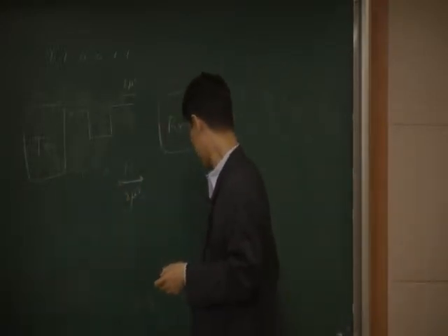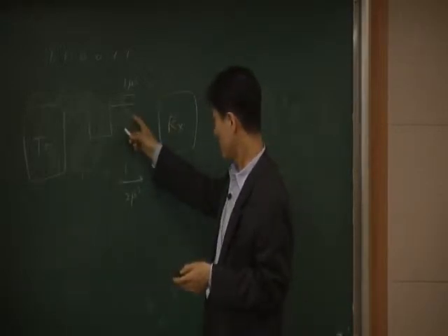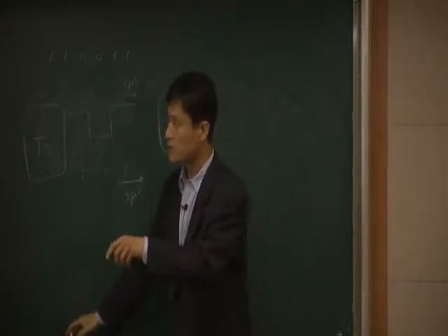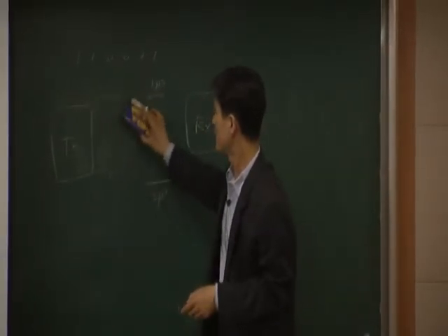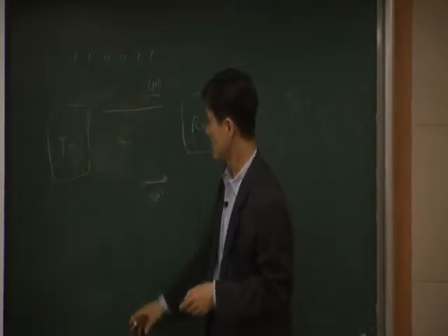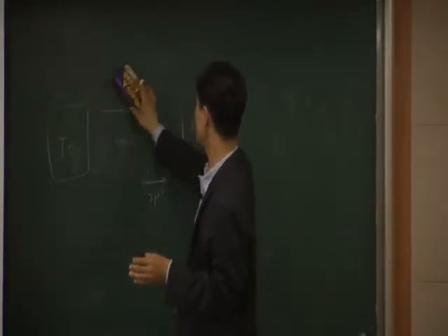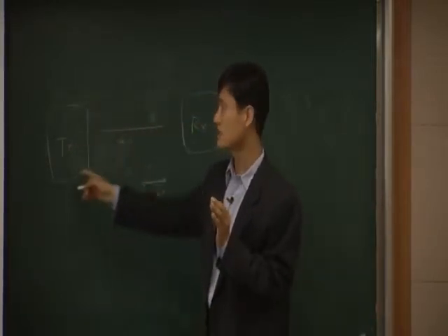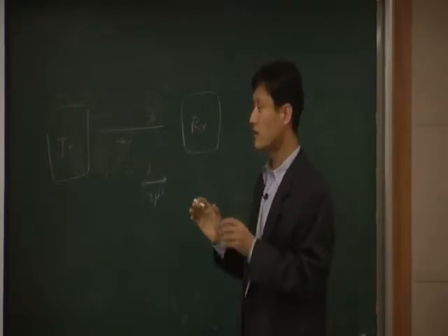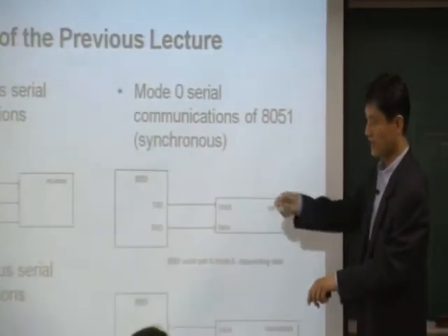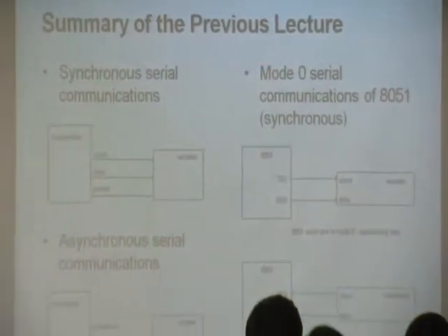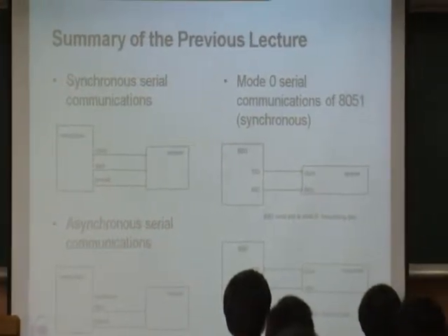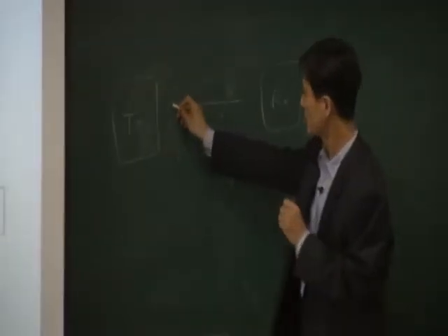And not only that, we have only 0 and 1 like this. Since there's no clock, what happens if the transmitter is not doing anything, not transmitting any bits? This is just a line, just a wire, so you may have a certain voltage, like a leak voltage. Let's say this is a ground voltage, 0 volts.